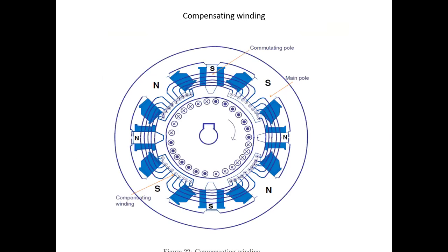Okay, you can see here the armature reaction effect. Commutating poles, interpoles, are also known as compoles. Interpoles' another name is compoles. What is the purpose of compensating winding? To reduce the armature reaction effect, we provide compensating winding, which is between two poles in the armature. Compensating winding or interpoles and compoles are both the same. In the schematic diagram of a DC generator, we drew interpoles also. What is the purpose of interpoles?